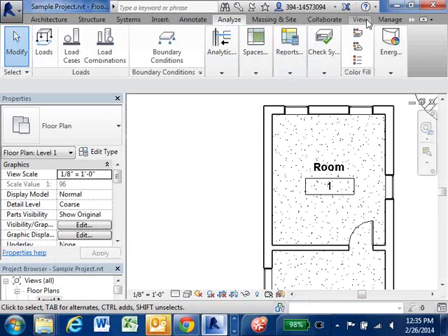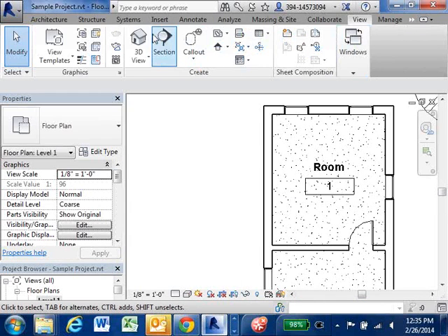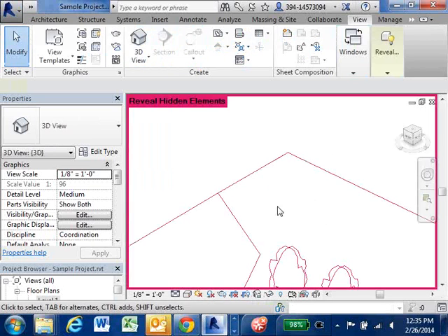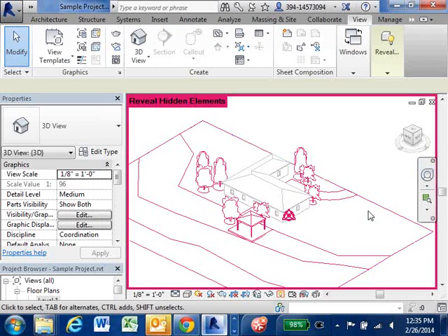Okay, so I've got a pretty simple model here that I've made, and you can see I've hidden a lot of elements, a lot of the landscaping elements, things that are not going to affect the daylight within it. If you're concerned about trees or exterior objects, you can create an object that's not on a landscape layer or an exterior layer, and it will be carried through. Like if you're worried there's another building or something like that that might affect the daylight, I would encourage you to include that. But a lot of this extra stuff you don't need. So I've turned that off.